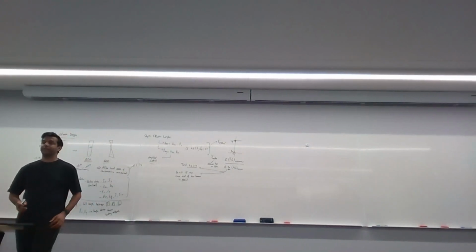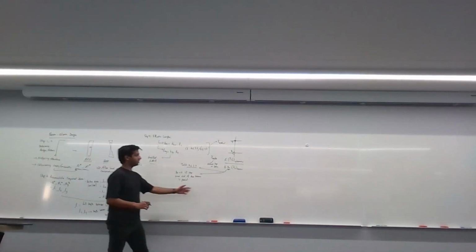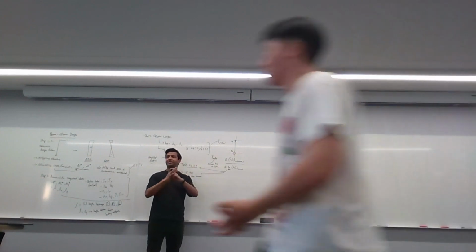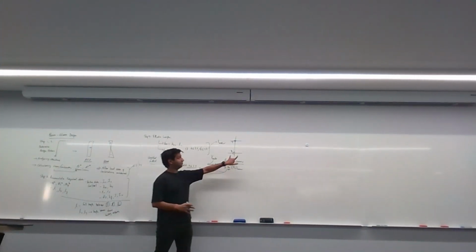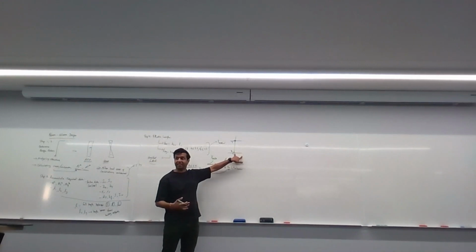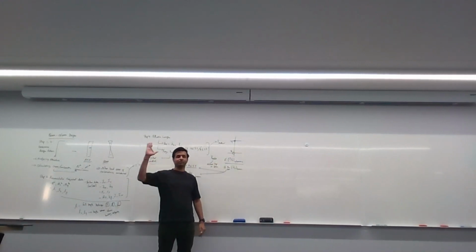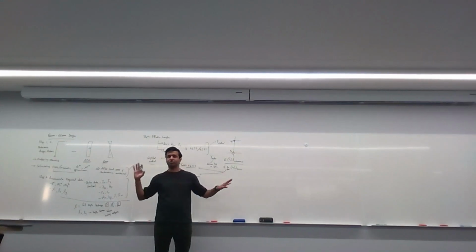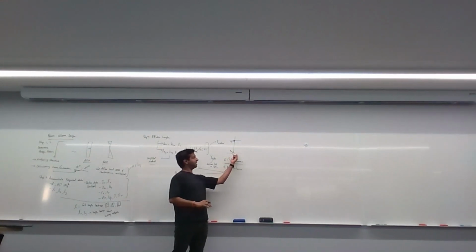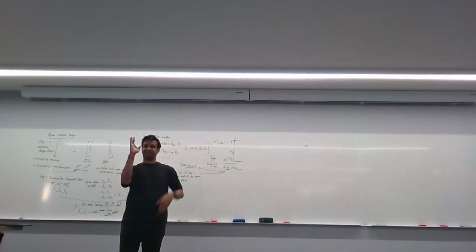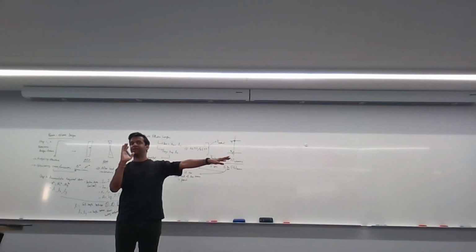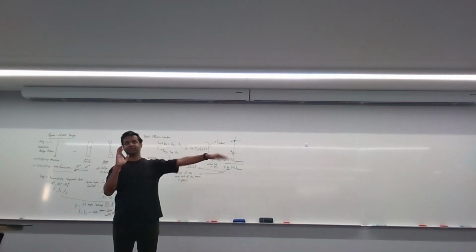That's very important to remember. If the near end of the beam is pinned to the column, it means that any bending that happens in that beam doesn't affect the column at all. Whenever you pin something, you've basically isolated those two parts of the structure. So if the near part of this beam here, for example, is pinned to this column, then beta E is equal to 0, because the column doesn't feel anything that's happening with that beam. If the beam wants to rotate, it'll just rotate. That's it.